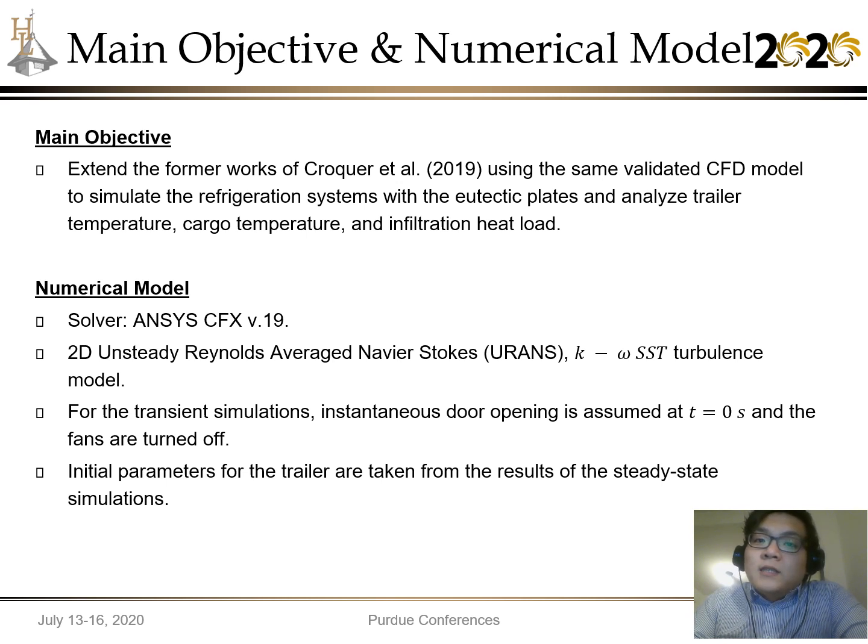For the numerical model, ANSYS CFX version 19 was used, which solved the 2D unsteady Reynolds-averaged Navier-Stokes equations, as well as the k-omega SST turbulence model. For the transient simulation, instantaneous door opening was assumed at time equal to 0 seconds and the fans were turned off. For the initial parameters inside the trailer, results of the steady state simulations were taken. For the steady state simulation, the doors were closed and the fans were turned on until convergence was reached.